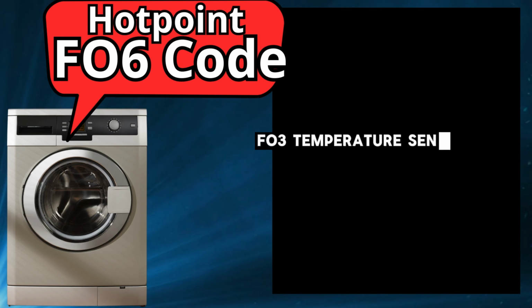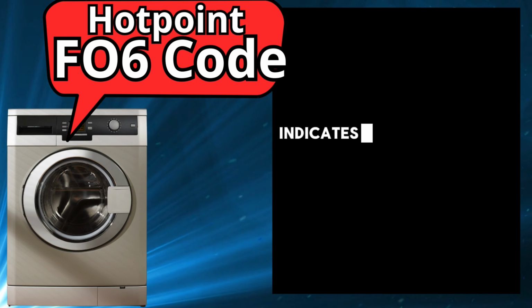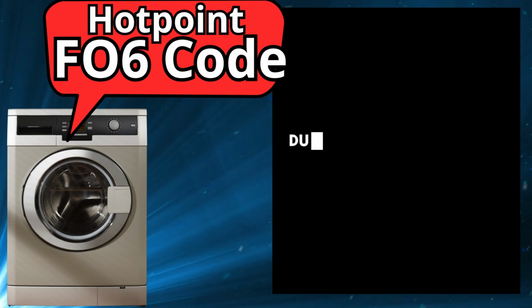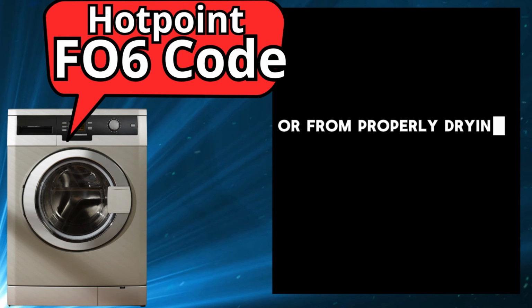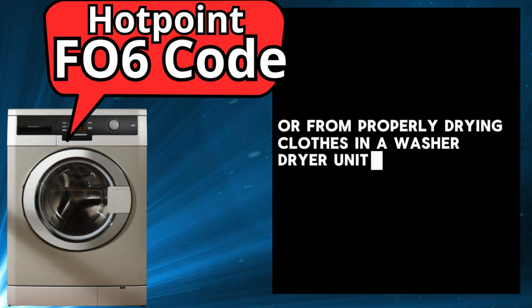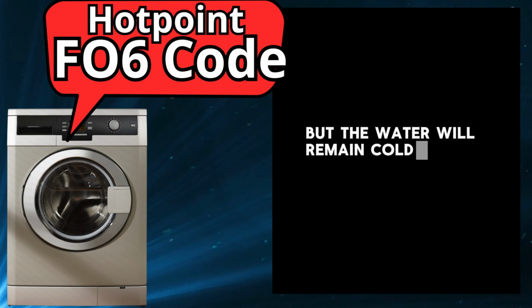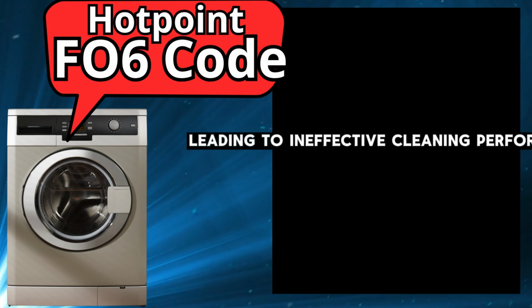F03, temperature sensor fault. This fault indicates a problem with the temperature sensor, preventing the washing machine from heating water during the wash cycle or from properly drying clothes in a washer-dryer unit. The machine may continue to run, but the water will remain cold, leading to ineffective cleaning performance.